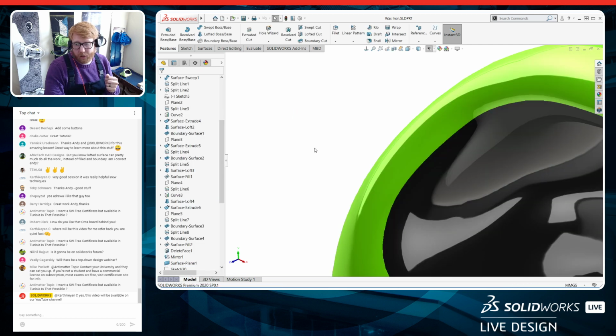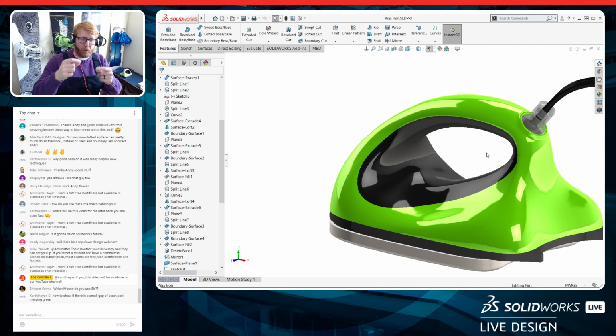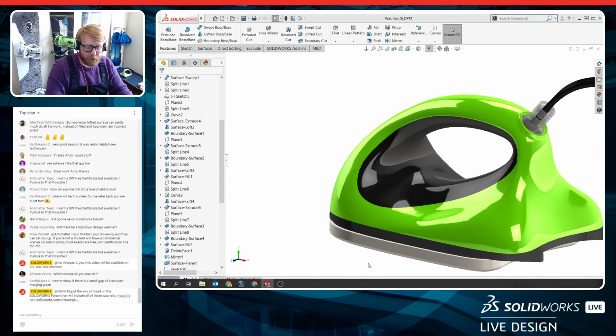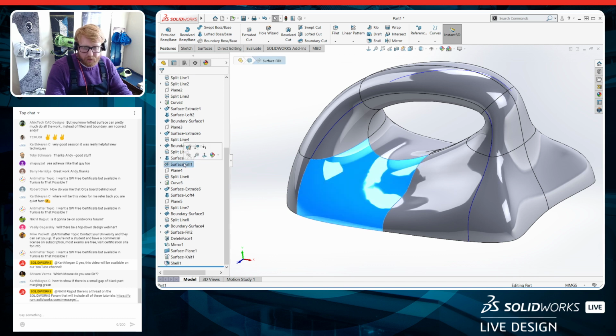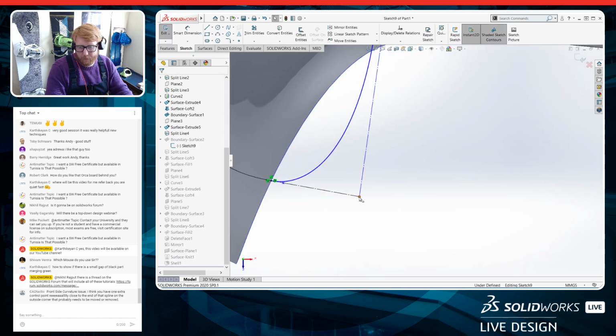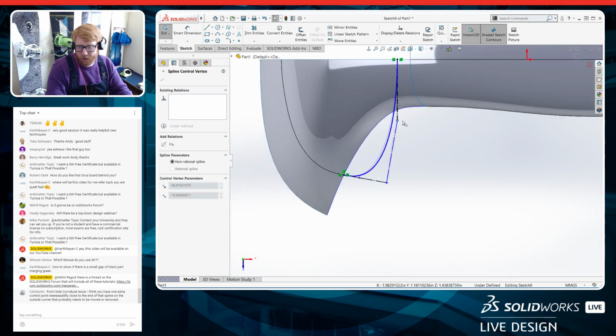But I'll be honest with you, I don't really desire to do it live right now, because changing that sketch may cause some other downstream things to fail, which are quick and easy to fix, but it's just kind of frustrating. You have to go through each one and any downstream feature that may have failed, and add in the coincident relation. Actually, let's try it. Let's get crazy. Why not? This is the whole point of this, to just do it live, right? So I think if I make it so the curvature is not so tight right there, kind of loosen it up.